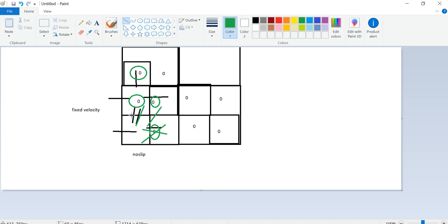But when OpenFOAM looks at this one, it says, oh, okay, I'm looking at more zeros. Is the flow supposed to go here, here, or here? Now if the mesh isn't so fine, OpenFOAM can fudge it by changing some of these zero values and increasing the velocity to make the flow go elsewhere, so that the solution can converge and be solved. But if you have such small boxes, OpenFOAM has to do this again and again, and you'll get really confused. You have to do it almost twice to 4 times as much if you just increase the mesh resolution.